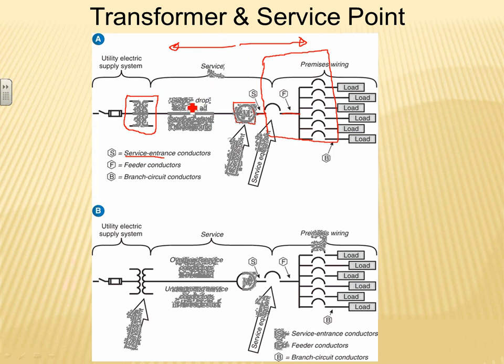They also have something called service drop, or overhead, or service lateral. These are pulled by the utilities into their meter termination box, the termination box or the meter socket. So this becomes the ownership of the utility. The utility owns up to here. So that's scenario number one.